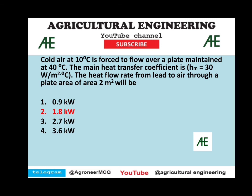So cold air at 10 degrees Celsius is forced to flow over a plate maintained at 40 degrees Celsius. The mean heat transfer coefficient is Hm equal to 30 watt per meter square degree Celsius. The heat flow rate from plate to air through a plate of area 2 meter square will be. So here the heat transfer takes place through convection. So for that we have formula hA delta T. So here h is heat transfer coefficient, so 30.